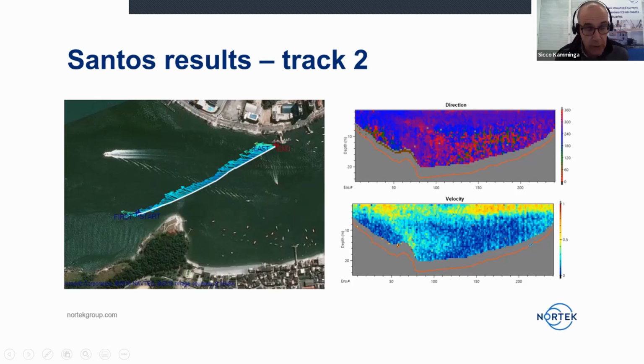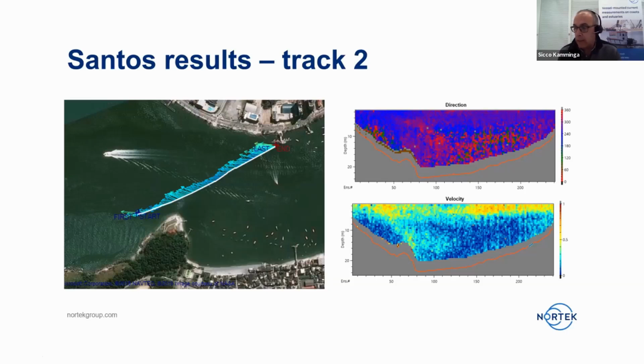So for more scientific measurements or for governmental measurements, you would do that for a long time. You would do that for like 13 hours, a full tidal cycle, and make these transects, maybe in 2 different tracks. So you have a nice image, you have time for these tracks, and you have 25, 26 nice consecutive images of the flow and the flow distribution in that cross-sectional area. And you can make nice flow maps and study what's happening.